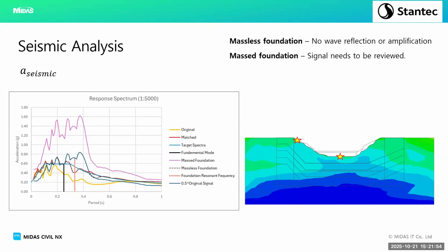Now, the mathematically correct way and geotechnically correct way is to do deconvolution. So essentially, you develop a transfer function which says, in layman's terms, I want this signal at the top to be X. I have X, or depending on whatever layers of foundation you have, what must be my input signal to get that? That's essentially what it's saying.